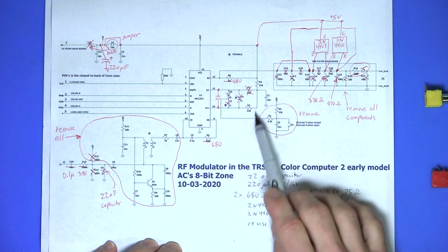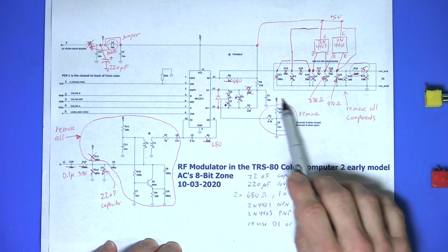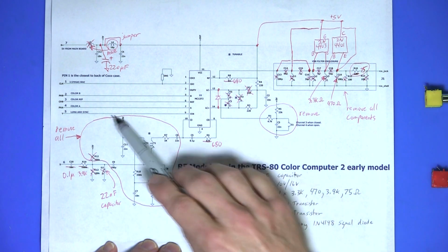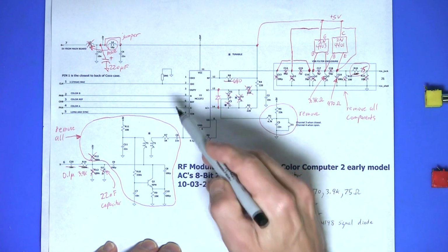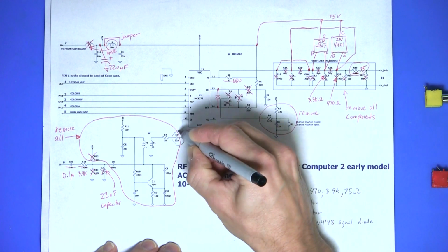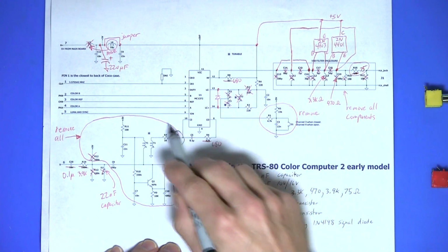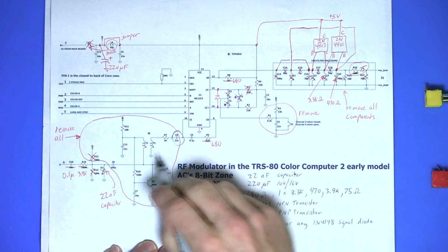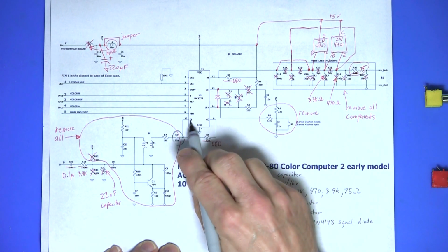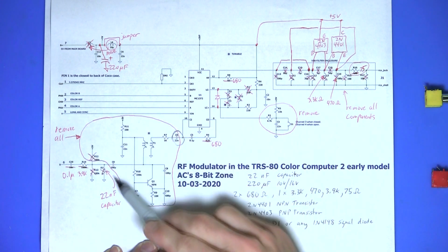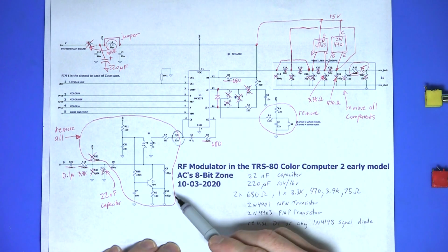There are some areas that are sort of optional to remove. You only need to remove this area and this large area here. Well, you always have to remove at least the C6 capacitor or R7 to isolate any of this, so you're not injecting anything into the chroma input. But a lot of the circuit is optional to remove.